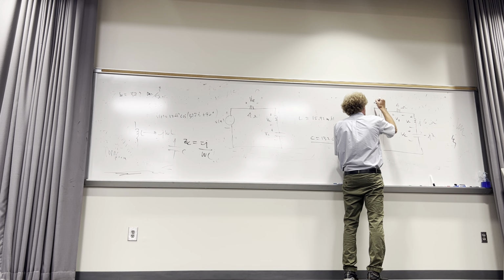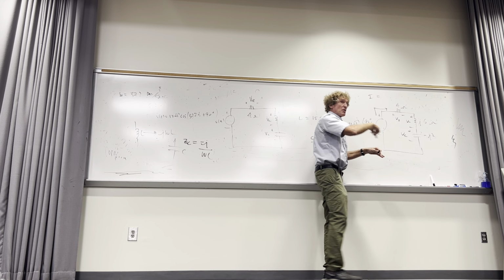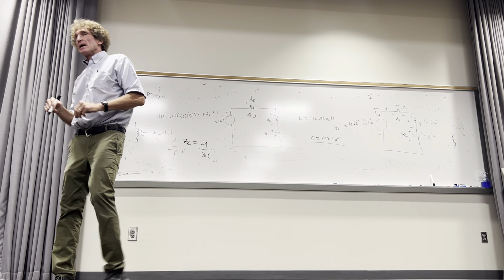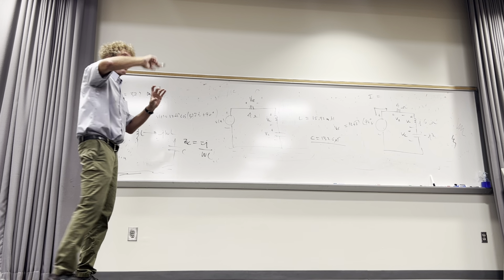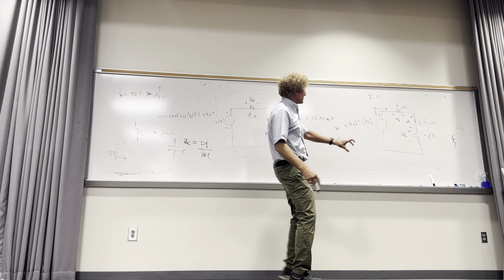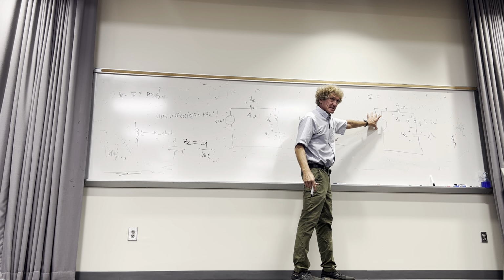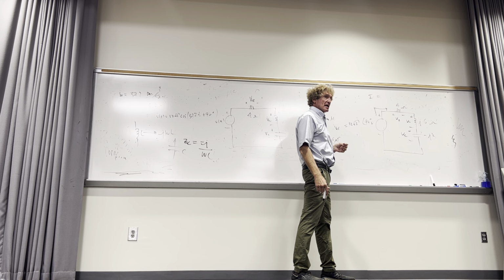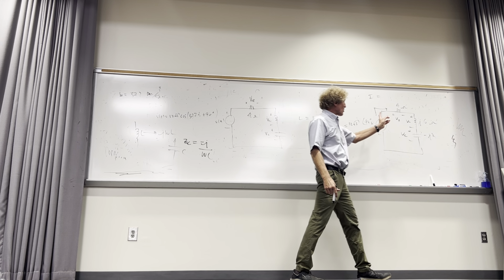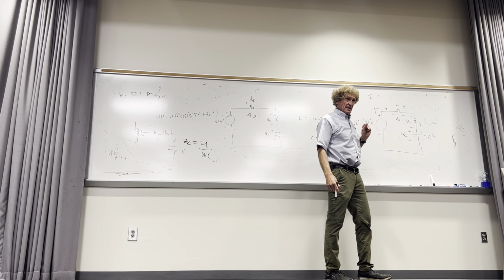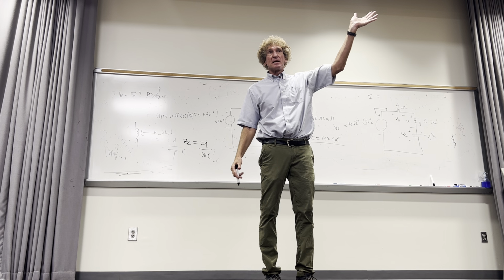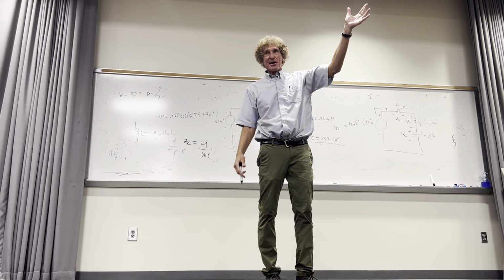If I want this current I, you'll notice we have one loop equation, one single loop. So the total voltage that would be driving that current is simply this voltage. It's 12 square root of 2 at 90 degrees. And what's limiting the current are all these impedances. Now, I'll get to the reduction in a second, but how many understand the thoughts?